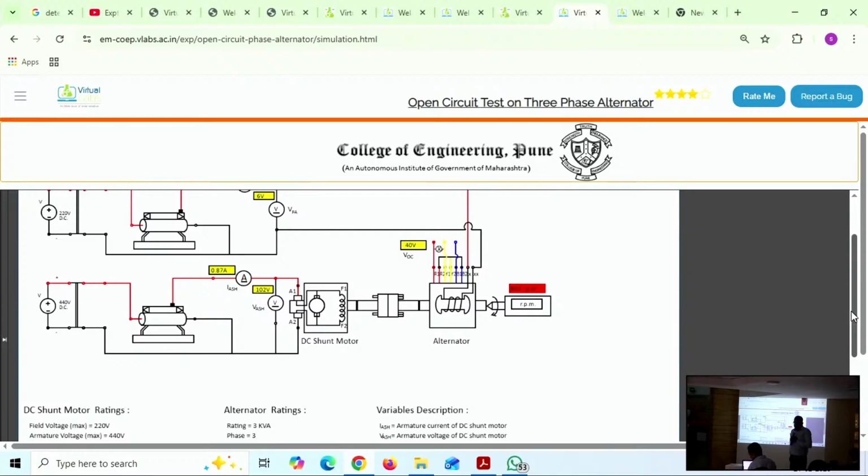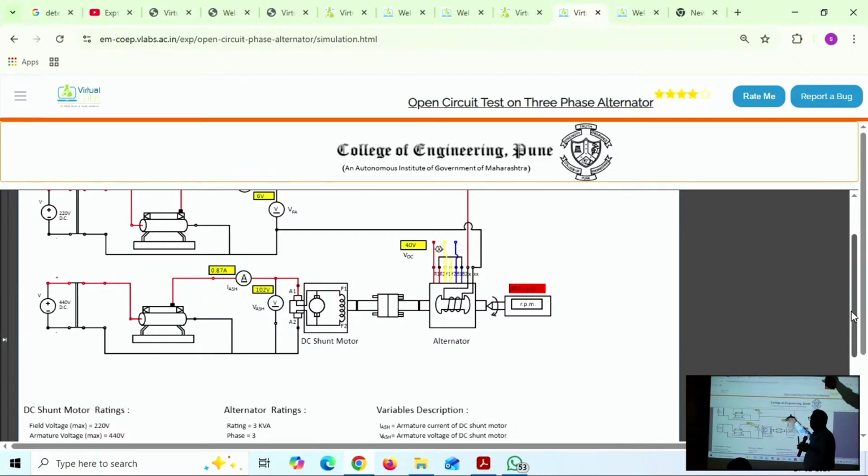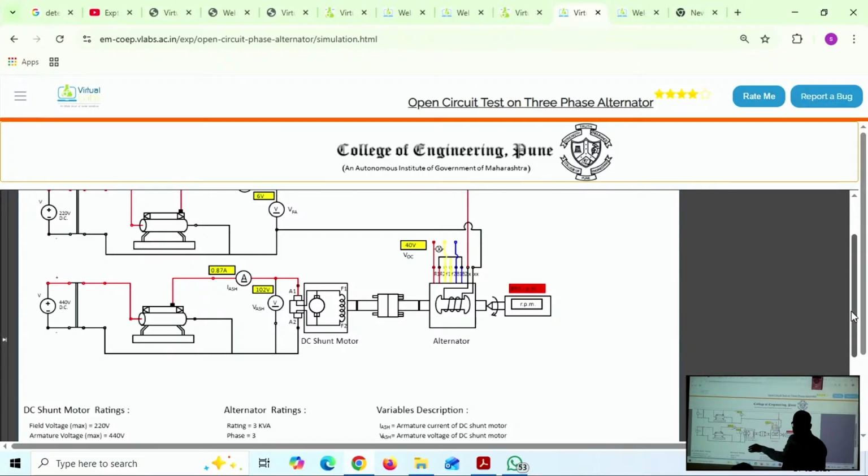As this sir expressed, field control is additional to this. Yes, if the flux is higher, then the speed would be lower. Flux is higher means field current should be higher, DC field current. DC field current should be higher means DC field resistance should be lower. Initially itself we are getting high currents. In that case, initially we are getting high currents, right? Our first objective is that currents must be taken care of first.